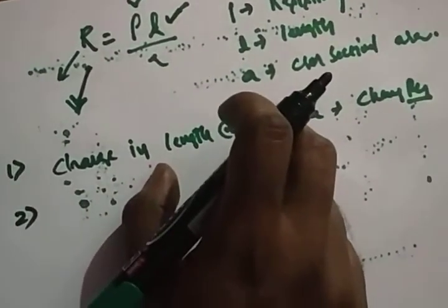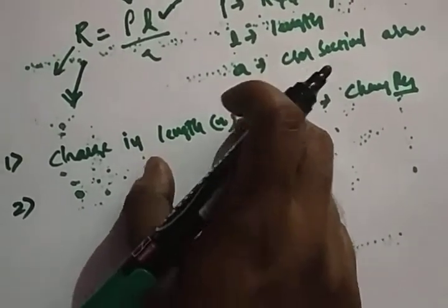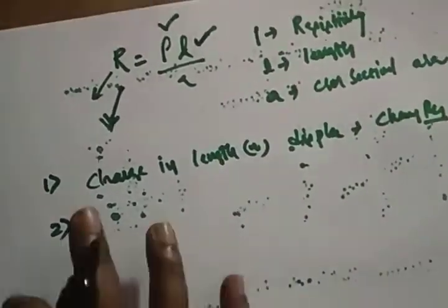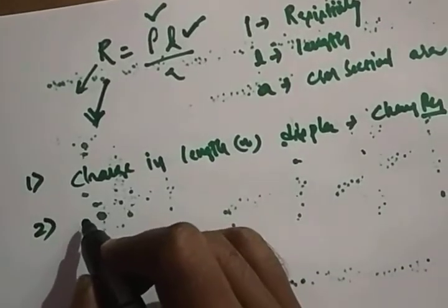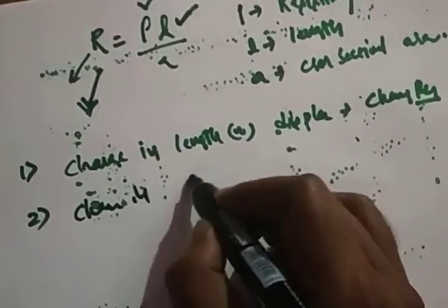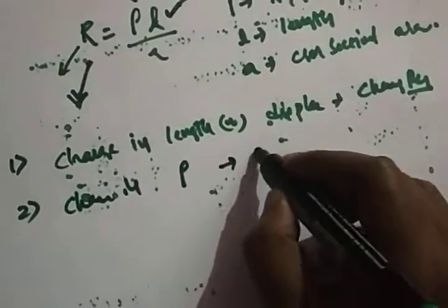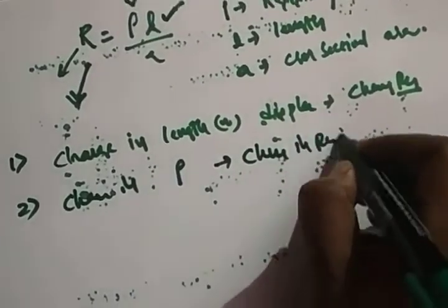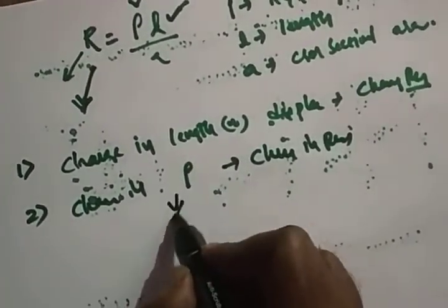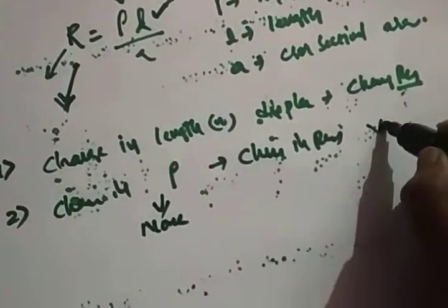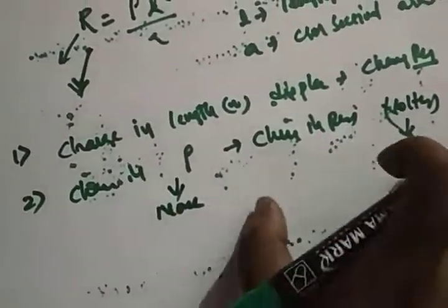That's it. So this length is a non-electrical quantity, so we can easily find out the non-electrical quantity, right? So resistivity, change in resistivity, so there must be a change in resistance now. If the change in resistance happens, you can easily find out the voltage, that means the electrical quantity. So the resistivity is a non-electrical quantity. Whatever voltage you are getting from the change in resistance, that is the electrical quantity. So that is a resistive transducer, right?